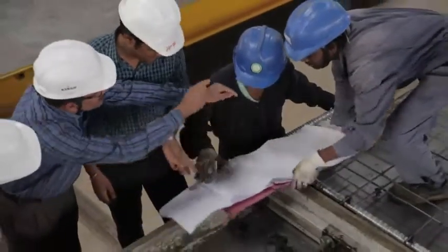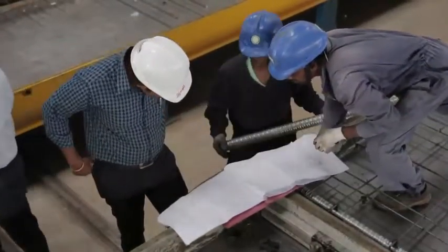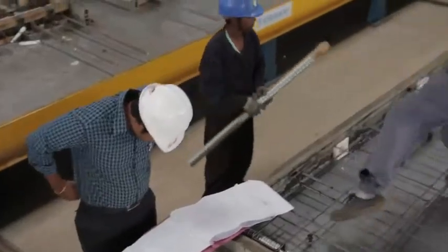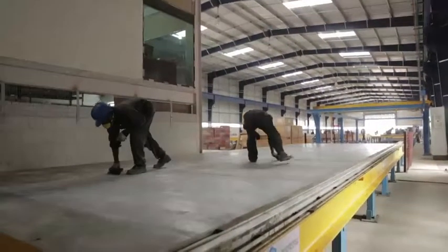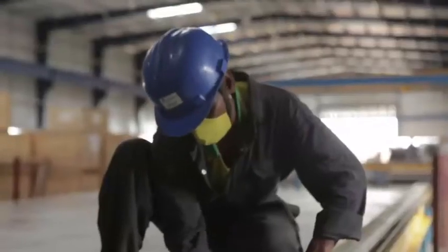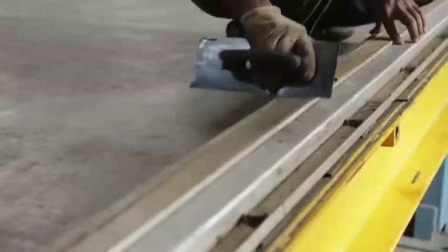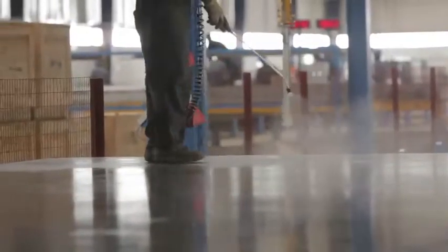Preparation for precast. Before starting work, the supervisor or the engineer in charge must examine the production schedule and drawings. Cleaning and oiling station. Precast pallets must be cleaned thoroughly. A uniform layer of releasing oil is then applied all over the surface. Check for any damages and pallet level accurately.